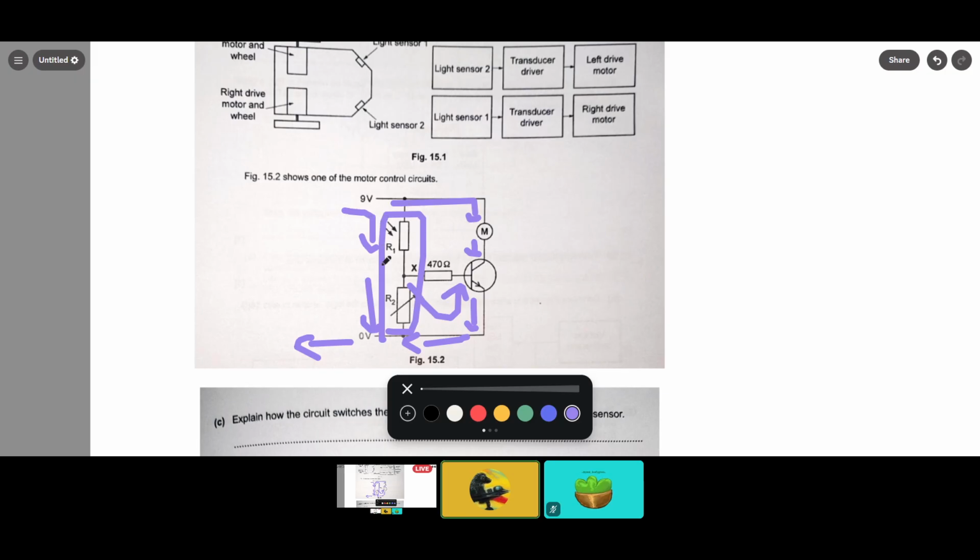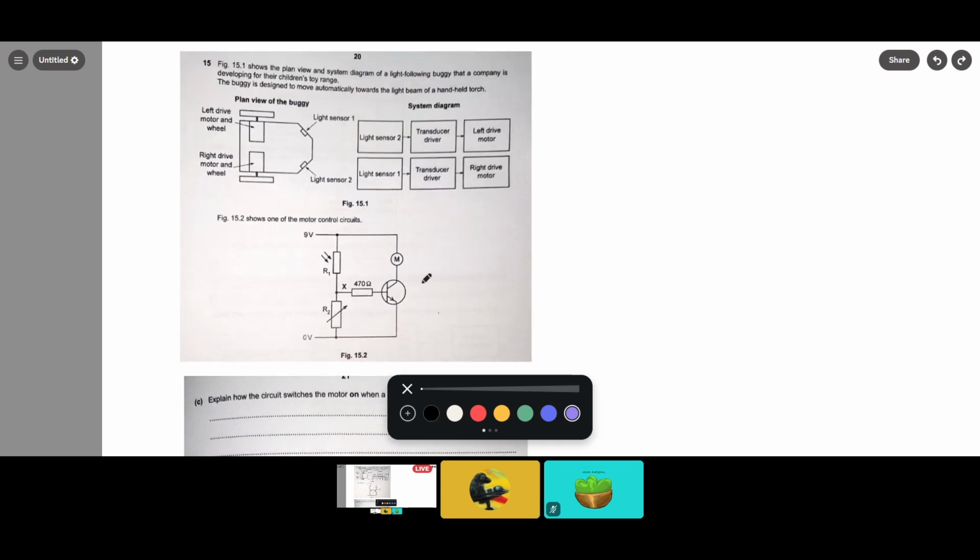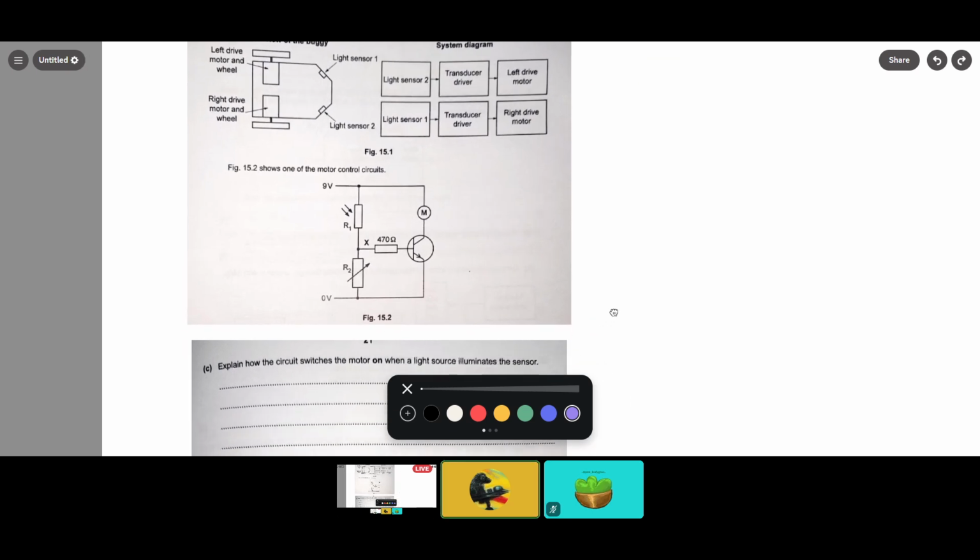If you notice any sub-circuits that you recognize, for example, this voltage divider, or this transistor driver for a motor, then you annotate that, and you can check if those two sub-circuits connect to each other, and in this case they do. So that's the basics of circuit analysis.